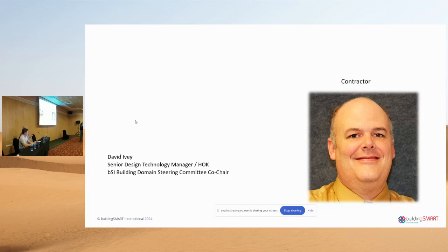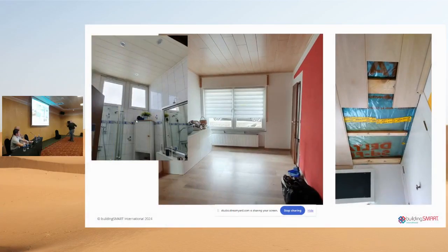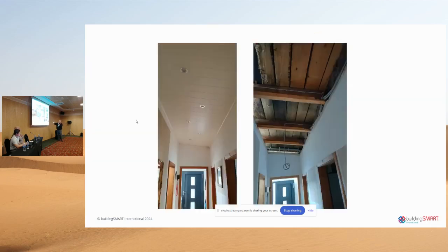Yeah. So normally we come in and we just start swinging hammers and trashing everything, getting ready. But we know from talking with the client that hired us that they're looking to reuse the wood panel ceilings up here in some form. And we've also gotten a heads up from our consultants that there may well be hazardous materials, so we're a little prepared for that. So as opposed to just coming in and wrecking the place, we're disassembling the ceiling, we're disassembling the door. We've taken a peek inside here, and we've seen that indeed there is mold in the ceiling, mold in the insulation.